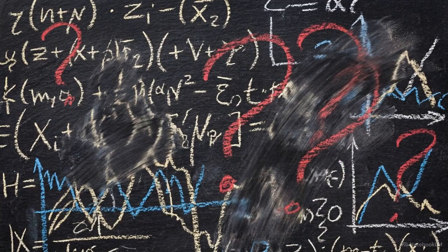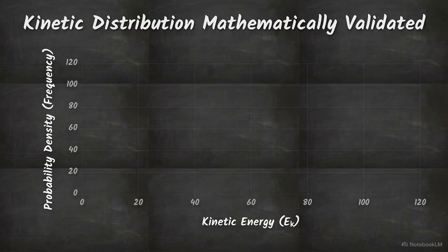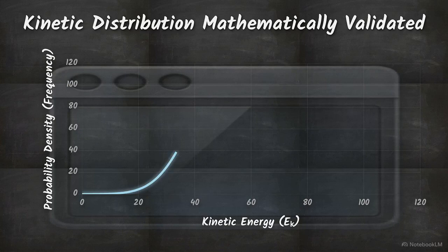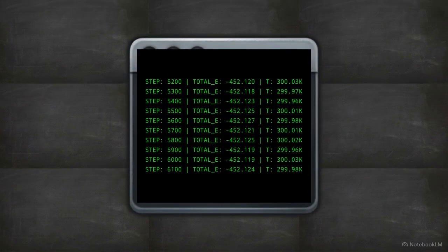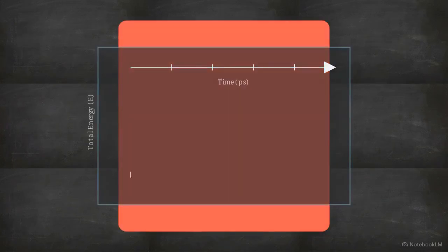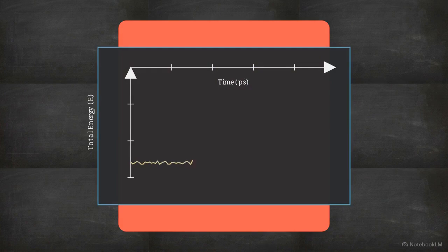Because of these paradoxes, a researcher cannot blindly trust the output trajectory of a coarse-grained simulation. Rigorous validation is mandatory. First, we must verify the system's kinetic energy distribution. This check confirms that the applied thermostat is actually sampling the correct canonical ensemble. This terminal displays the results of testing the time-step dependence of energy conservation. A failed integrator test, highlighted here, indicates a Hamiltonian drift. This test detects long-term integrator drift, an instability frequently caused by the mathematically smoothed potentials used in coarse-grained models.